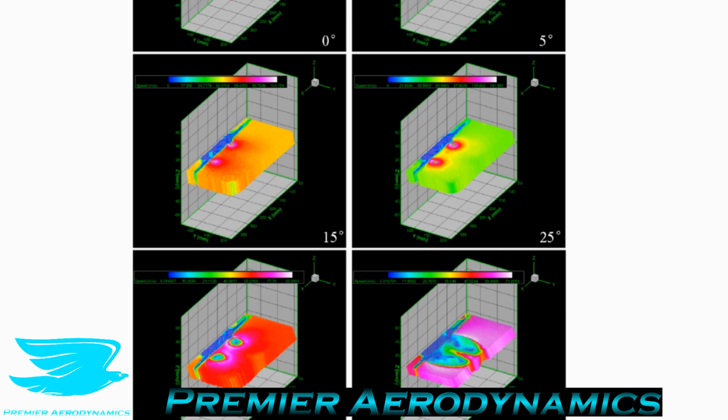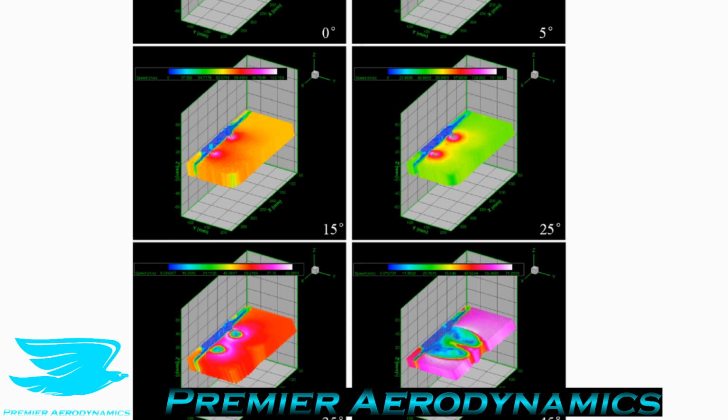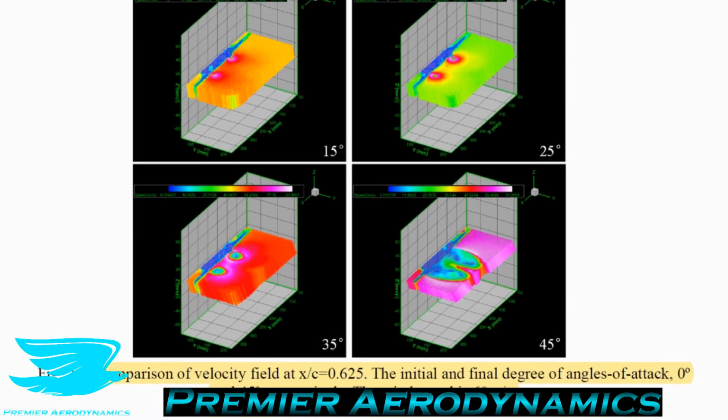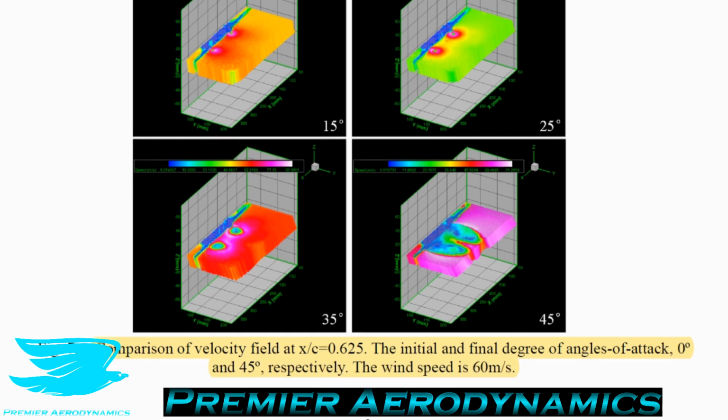Over a delta wing, you get two vortices forming over the leading edges. And in these vortices, the velocity is very low, but these pictures show that around the vortices, the velocity is actually really high. So you have the core, which is very low, and then around the actual core, you have a very high velocity. I haven't seen that before, and that's quite cool. And then when the vortices break down, the velocity around them is a bit lower. So that high region of velocity is probably due to these vortices inducing the flow around them.